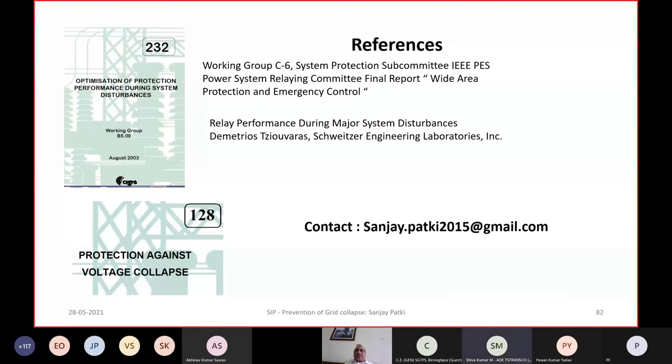And these phase overload relays, as per the recommendation of the CBIP manual as well as the CEA recommendation, we should have for all critical lines only distance relay as main one, main two, and overcurrent earth fault relay as a backup. Otherwise, there is an inherent backup protection in the distance relay itself. The phase overcurrent relays can malfunction during system contingencies the way it has happened in this particular case.